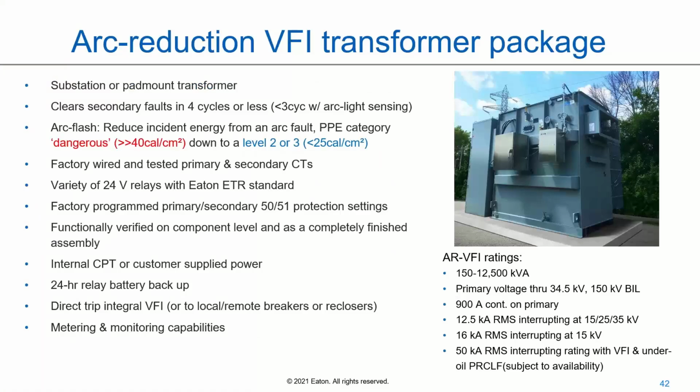And from a product scope standpoint, we go as low as 150 kVA. We can do it for substation style, which is shown in the picture, or pad mount style. And we can go all the way up to 12.5 MVA. So pretty much any of the 3-phase transformers we make, up to 35 kV and 150 kV BIL.